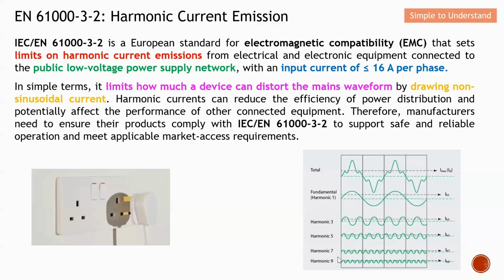So you can imagine that if all these currents add up, they look like a waveform that looks like this. So this is totally out of the sinusoidal waveform of the fundamental. This doesn't look like a sine wave anymore. So this can be a key issue, and all this disturbance from the harmonics can cause some disturbance for the mains. Therefore, we need to be very careful when we connect our device to the mains.